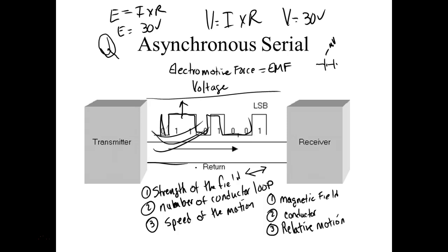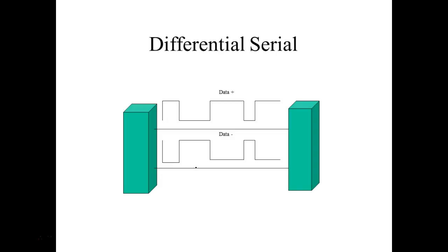So the technique they understood, and this came with electronics, we came out with a special amplifier called a differential amplifier. What happens is we never use 0. We don't use a common. What we do is we transmit the signal, two of them 180 degrees out of phase, so the opposite of each other. So this would be my signal, and notice the other one is exactly opposite. So we always have a difference of potential. Since we have a difference of potential, that means we can send current, right? Does that make sense? But we don't use common.